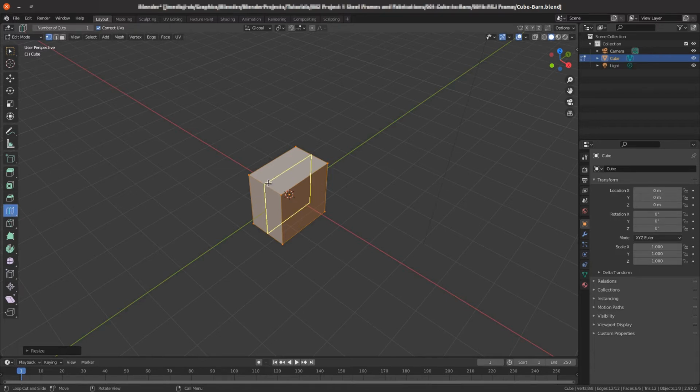The shortcut for this is Control R, but my screen recorder has taken control of that one, so I'm using the menu, and it gives you an indication of where the loop cut will be. We'll click on that to make the loop cut and then enter, and we've got the loop cut around the cube. Go back into select, and that gives us a center line.